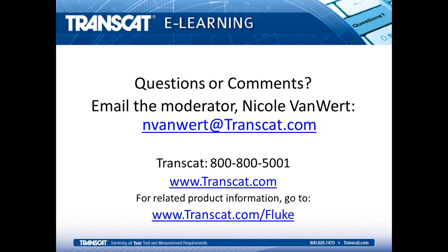Okay. We kind of talked about this one, but I will ask it anyway. What if you have multiple thermocouples in one dry well? Would you suggest keeping them all in the middle or calibrating them individually? Yeah, that's a good question. A lot of times with thermocouples, people will bundle them together and put them all in one hole, and I've seen it done both ways. Sometimes they can be really small in diameter, so if you don't have an insert with that many small holes in it, it's advisable to put them all together in one hole.